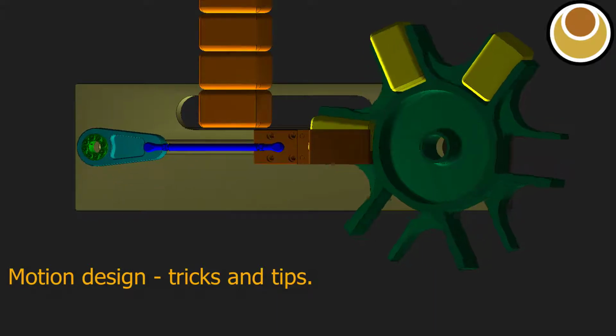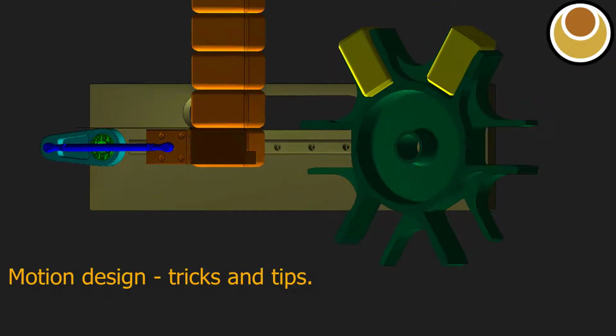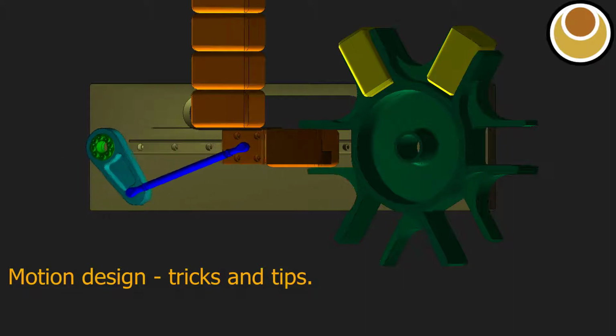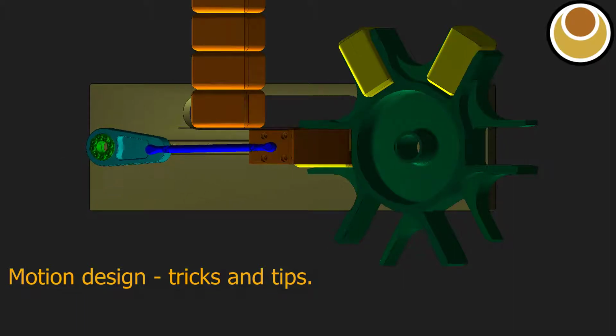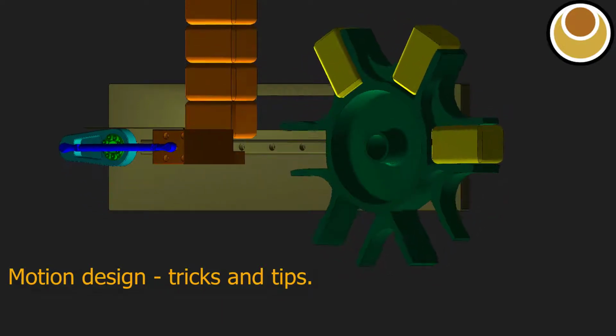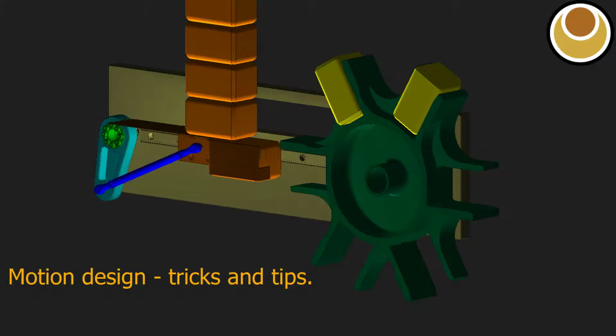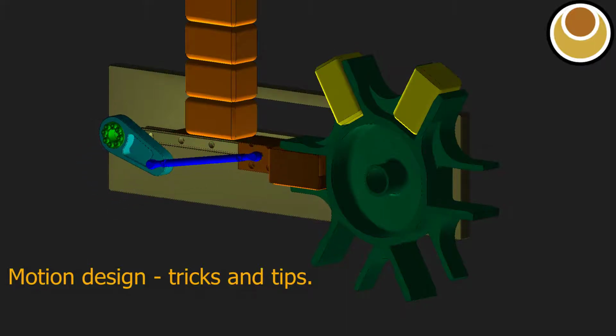Motion design is the process of defining the nonlinear cyclical motions of specific elements in the machine, typically cams or servo motors. The mathematical functions defining these movements are usually generated by software. Mechanisms such as four-bars can be designed to develop non-cyclical motion, but these are intrinsic to the mechanism's configuration, and I will not be discussing these techniques.